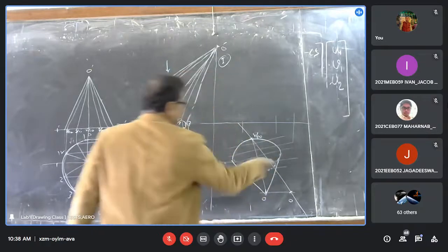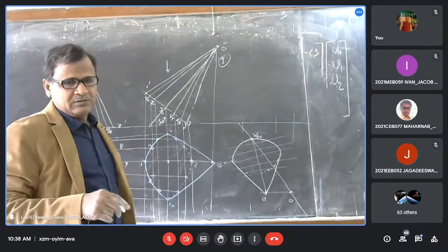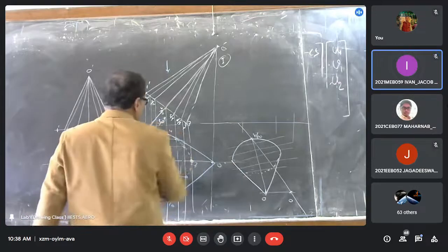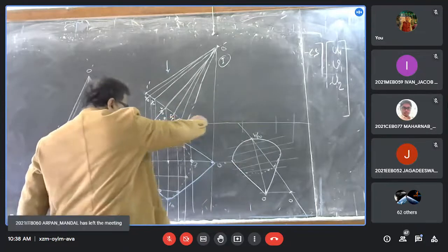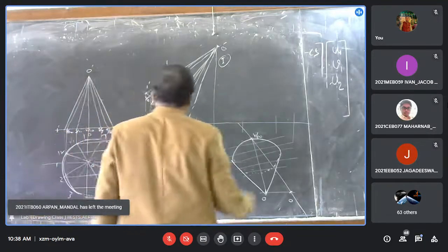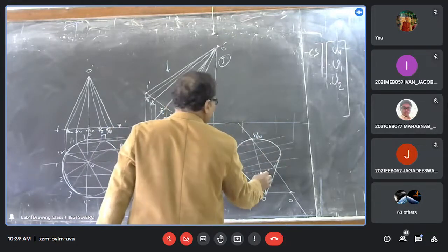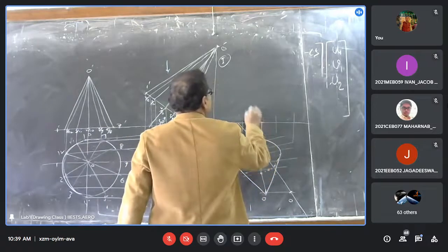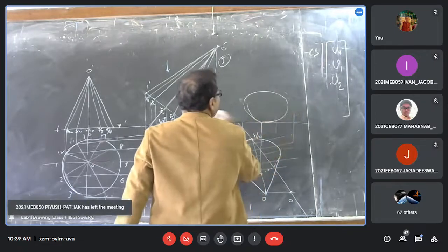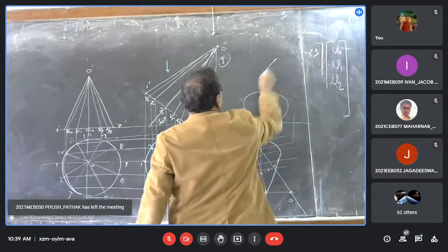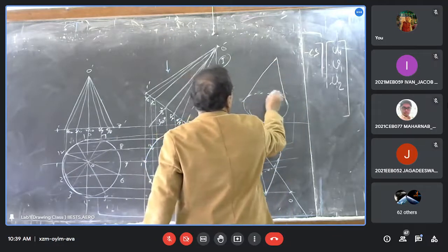I think I discussed with you how to copy this, the circular lamina, ellipse, and perpendicular line copy. Then draw the projection. You find the rotation is forward, so you cannot see the base. This is the resting point, point 7, and it is coming like this, and the vertex is coming here. You cannot see the base, so it is coming dotted.